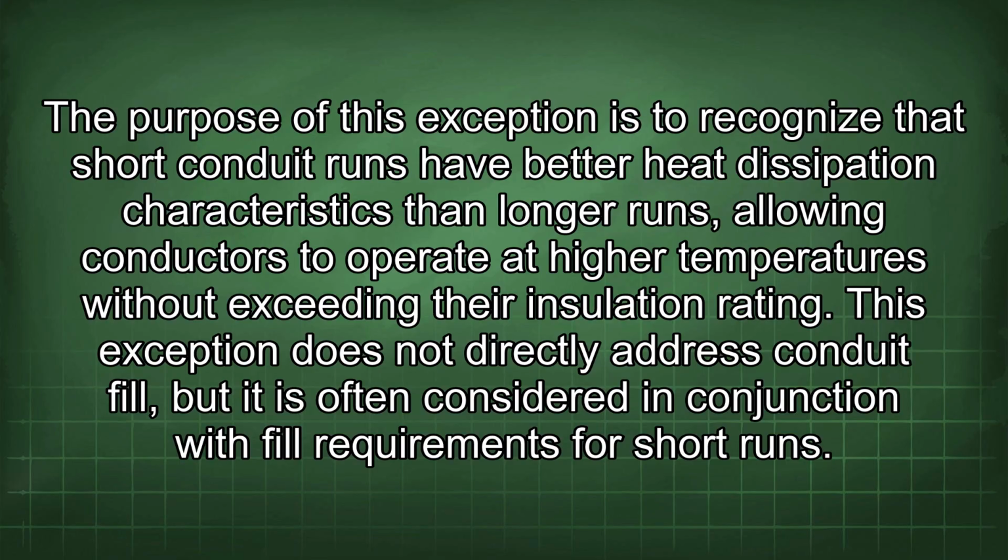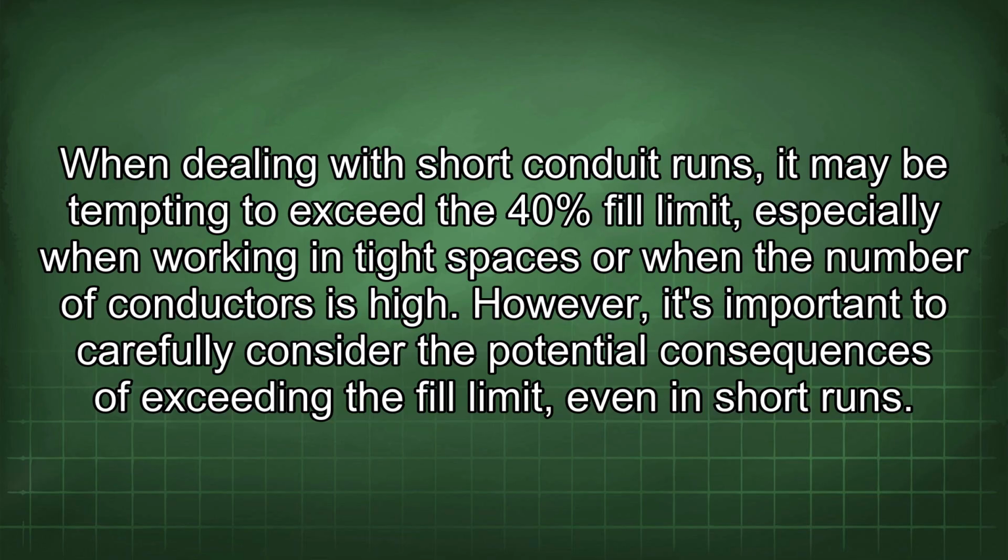This exception does not directly address conduit fill, but it is often considered in conjunction with fill requirements for short runs. When dealing with short conduit runs, it may be tempting to exceed the 40% fill limit, especially when working in tight spaces or when the number of conductors is high. However, it's important to carefully consider the potential consequences of exceeding the fill limit even in short runs.